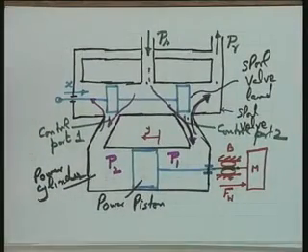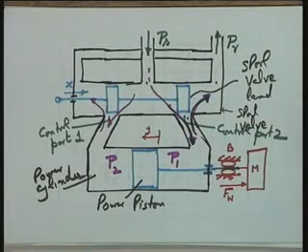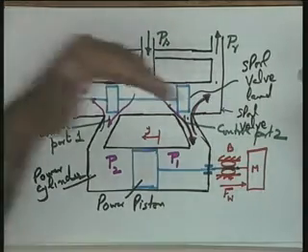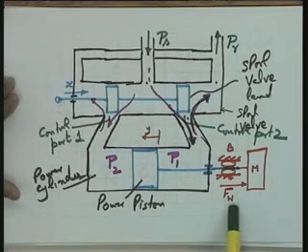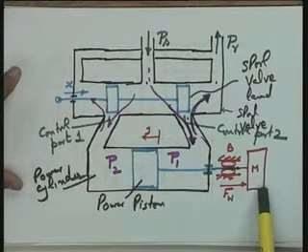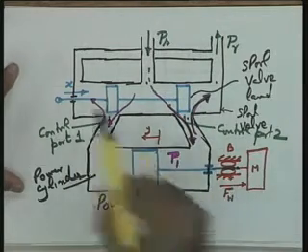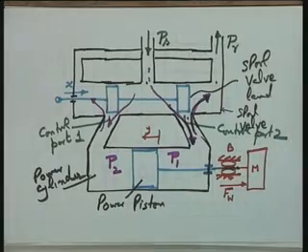Okay. So, having established the system working at the steady state, now let me disturb this system. How do you disturb the system? You can disturb the system intentionally, that is by movement of x. That is your commanded position will also change, this will perturb the system from the steady state, or the system could be disturbed by the disturbance force on this particular mass or the load. If a disturbance force acts here or the command changes over here, the pressures P1 and P2 will change.